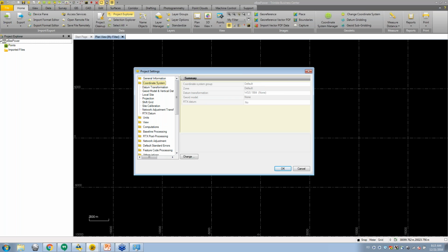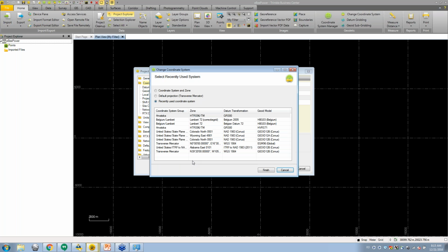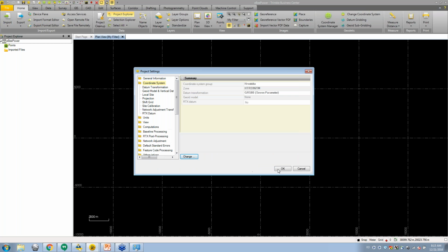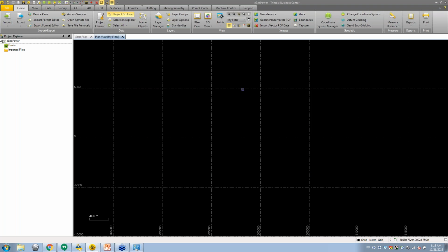And so this is the next important step, and this is setting of your coordinate system within TBC. You can actually start and run a project within UASMaster, bring your products in, set your coordinate system there, but we do not encourage that, as you can import incorrect data. So we set everything in TBC and then send it to UASMaster, but that's more of a workflow for advanced settings. So I changed the coordinate system to the Croatian coordinate system that we got from one of our customers.